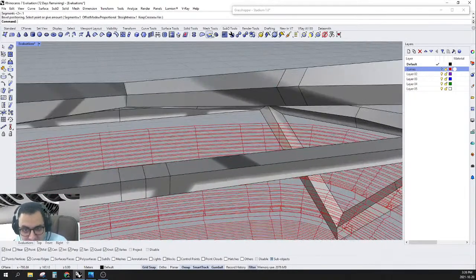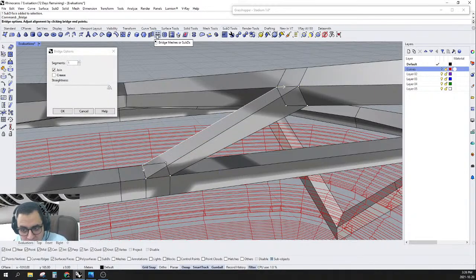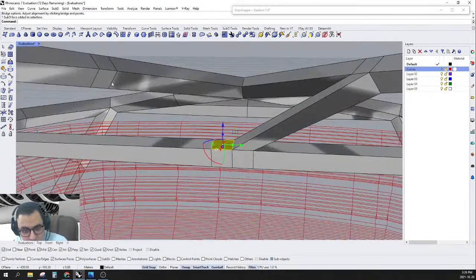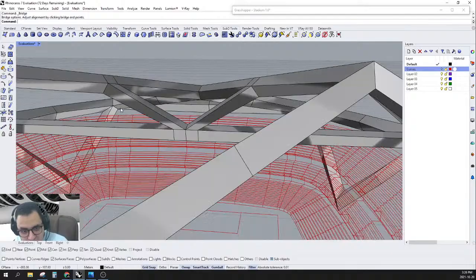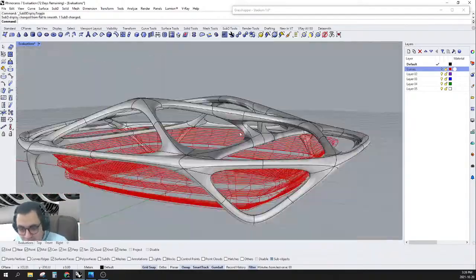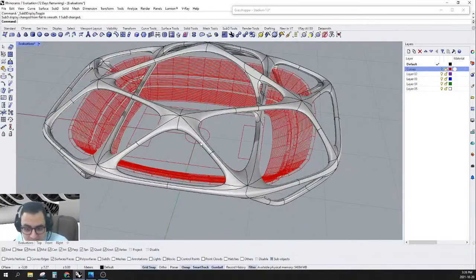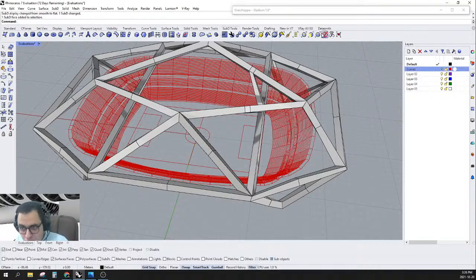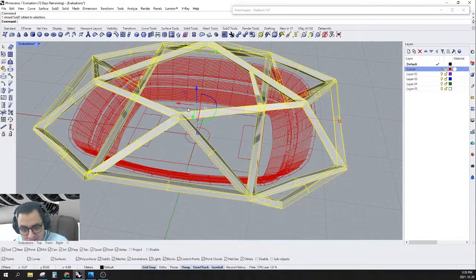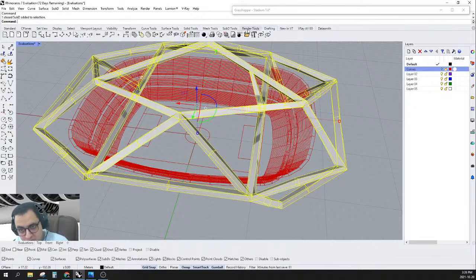And after you did this, you can simply select those faces, one right here and one right here, and bridge. Okay, and select this one right here and one right here and bridge, so it will look like this member is supporting those. We can simply go to select none and select this sub D and reflect what we have done in here.